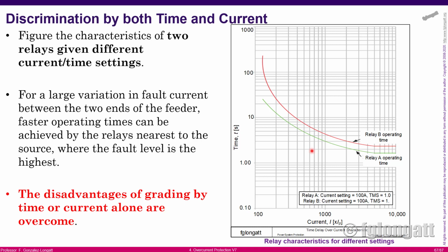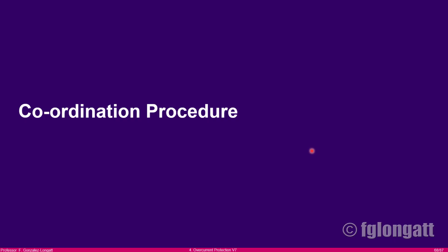Now, what is the problem? The problem is that you must have a very good model of your power system. Then you need to clearly identify the scenarios that allow you to get maximum and minimum short circuit levels. And you must also understand the configuration of your system to identify the longest time within which you must trip a circuit breaker. That is when the situation starts to be difficult.